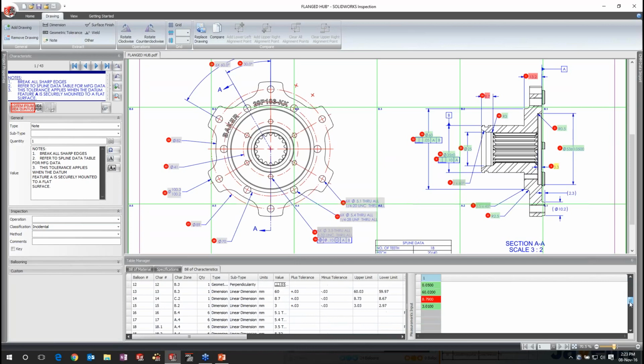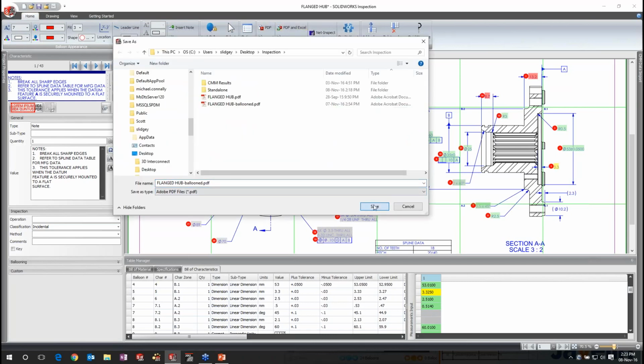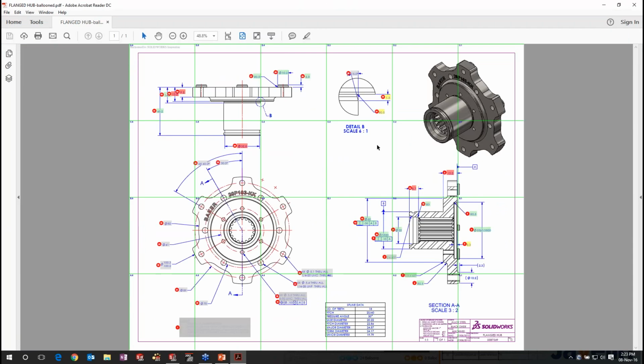And so there's the values that we took from the CMM, and then we could go back and do any of the manual ones through digital caliper or visual through the missing cells here. But now you can see again how it's nicely color-coded. So now when I go out and do the exporting of a PDF and Excel, now we've got the color-coded, nice presentation for a deliverable to a client, let's say, in the PDF format.